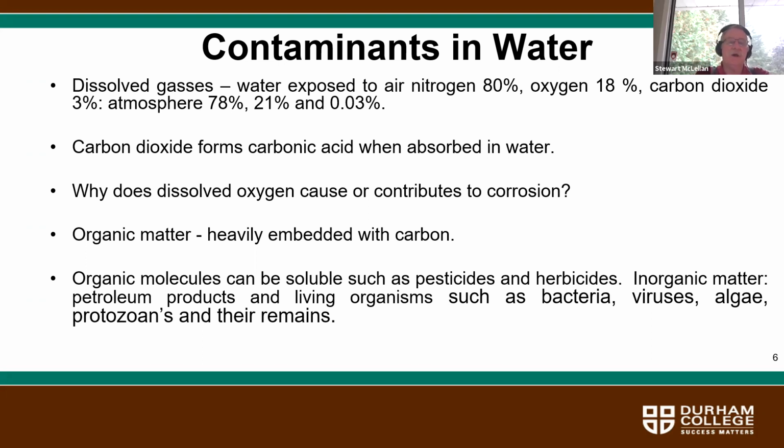The one important thing to note is if you have iron and oxygen in a 100% dry environment, you do not get corrosion. You need iron, oxygen, and water in order to get corrosion of iron. The atmosphere contains enough water vapor to cause corrosion, but it becomes even more of an issue when you're actually moving water that does contain dissolved oxygen within it.